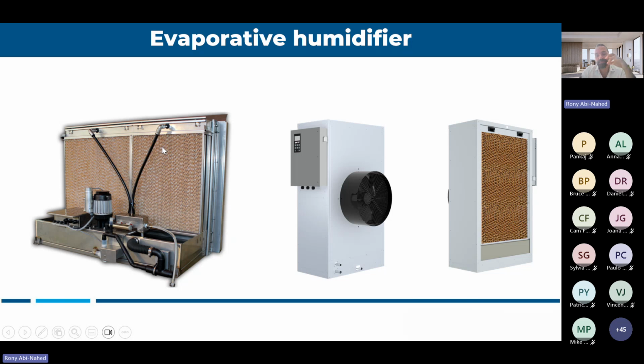So we can mix city water with RO water to get the purity from 99% pure water to 90% pure water. So you're getting the water a little bit dirtier, to preserve the media so you don't deteriorate your media. Now, another option you have with evaporative media is what we call a standalone unit. So instead of installing it inside the duct, you can have a fan directly on the unit, and then you can install it in the space.